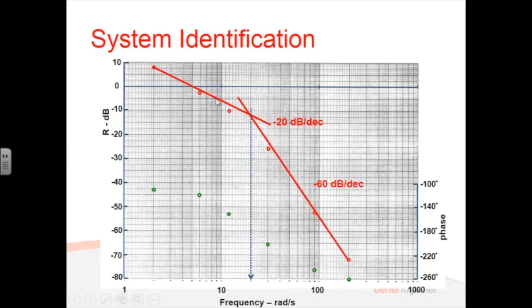Conversely, if you don't have the luxury of having the 1 radian per second point, you can work it out. Because if all we had was that line, then the whole transfer function is K times an integrator. 1 upon s, for a sinusoid, is 1 upon j omega. So G equals K over j omega. That's got 3 variables in it. If there's any point on that line where I know 2 of them, I can work out the third.